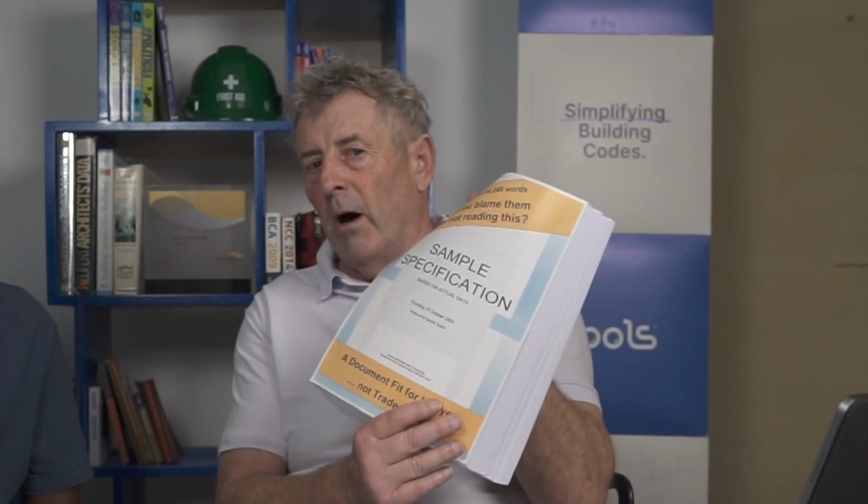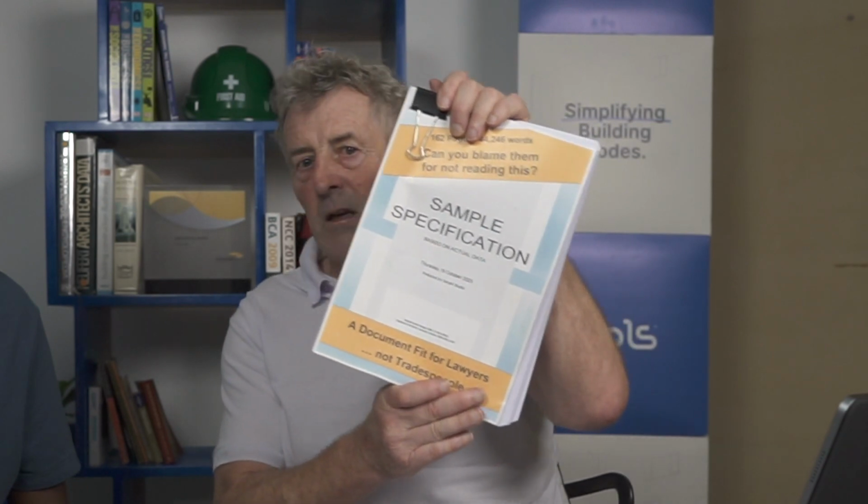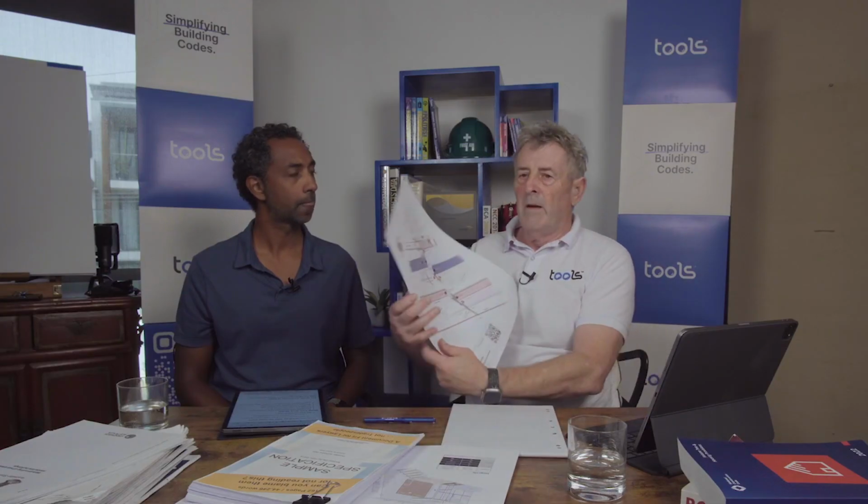No. He might have a fantastic drawing that sets out the height, the width, the size, what components and what materials are going together. That's great. He passes that on. But the way they're put together, it's never in there. The nuts and bolts, the North Star of the information is not in there. They need this granular knowledge about the height of a water stop angle, the depth of a sealant, and the willingness to go and do the work necessary to find out the knowledge that complements the instructions from the designer under the umbrella of specification.